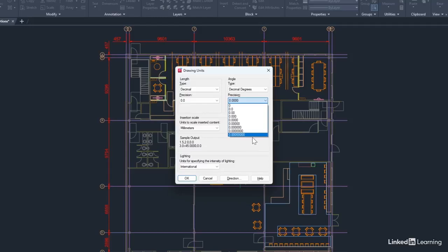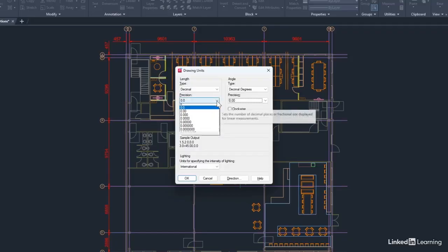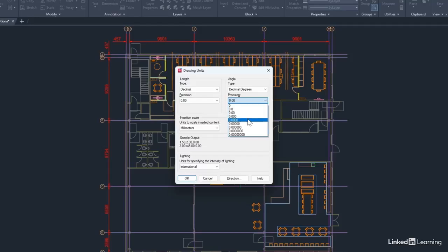That 0.12 of an angle, as you make that angle bigger and wider, does become, in essence, a slice of pie that gets bigger and bigger, coming out from the center of a circle. So you might want to double up there on your precision. So you might go to 2 decimal places. So if I was using 2 decimal places for length, double it up for your angles to 4. And the reason I say that is it just means you're being really precise in your drawings.